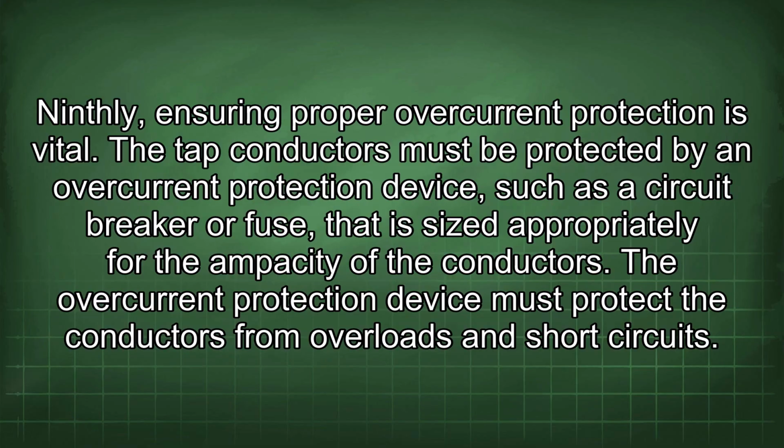Ninthly, ensuring proper overcurrent protection is vital. The tap conductors must be protected by an overcurrent protection device such as a circuit breaker or fuse that is sized appropriately for the ampacity of the conductors. The overcurrent protection device must protect the conductors from overloads and short circuits.